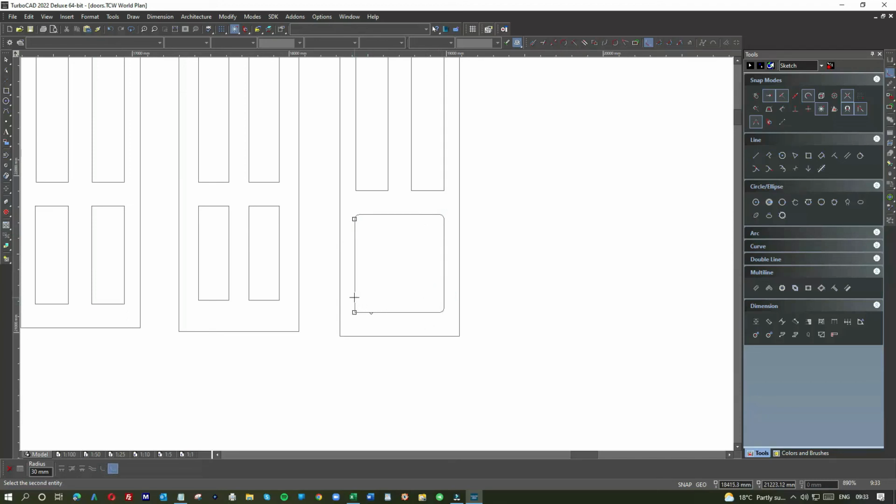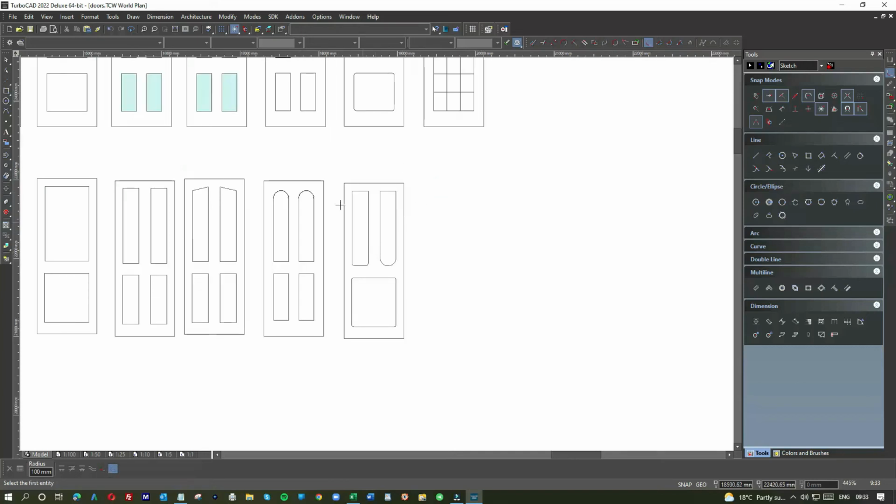If you're doing a panel door, sometimes you're going to get the curves. So it's very simple to apply. Change the size of the fillet, and you get a different look. Theoretically, I could have done that when I was doing this one, but I wanted to show you other ways of doing the same thing.